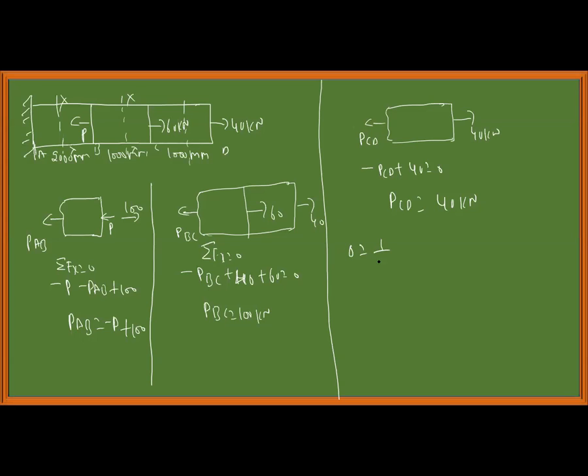We'll calculate the deformation directly. 0 is equal to 1 by AE into PAB LAB plus PBC LBC plus PCD LCD, same problem.